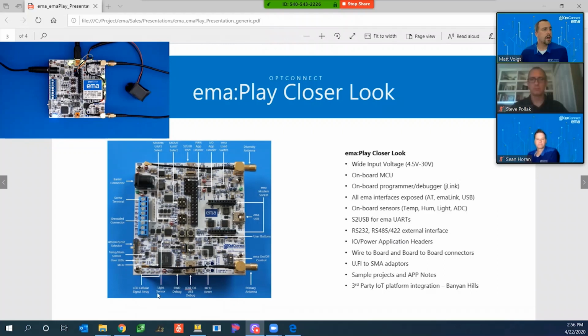And so moving down here, there's an onboard microcontroller. That guy's right over here. This is a 32-bit Atmel Cortex M4F microcontroller. It allows you to write your own applications, which is what we've done in this instance. It's running our demonstration project. You can see the LED signal array down here is lit up with 2 LEDs. It might be a little tricky to see. And so it's indicating OK signal. And in the picture, the LED signal array is right here.